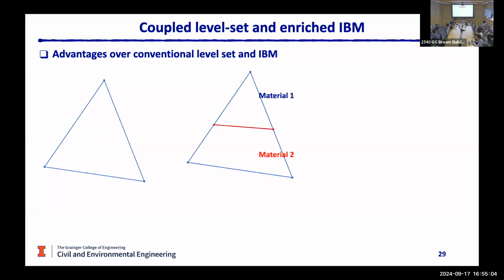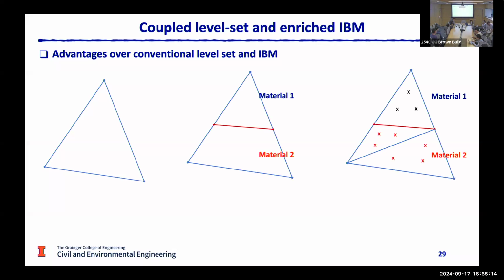The reason is, if you look here, the nodes of the immersed triangulation are on the edges of the background cut cell. So we can break the bigger triangles into smaller triangles. Then, because you have those standard triangles, you can apply Gauss integration for standard triangle elements to do the exact integration over those small triangles. So that's what I mean by this small cut element issue being remedied. Do I answer your question?